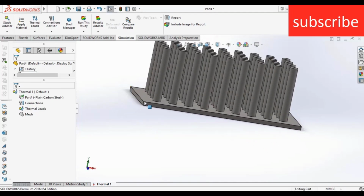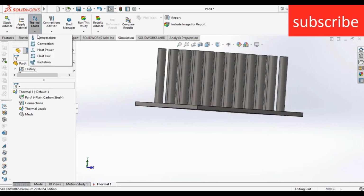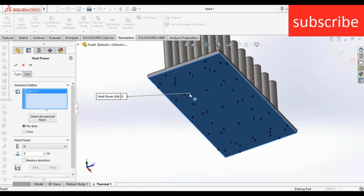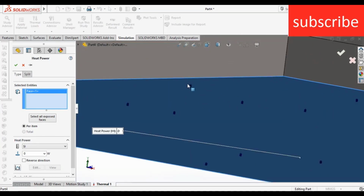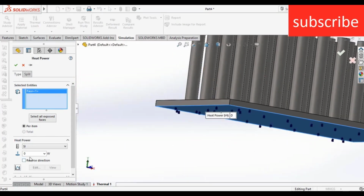Now the first thing I'm going to do is apply a load. Click on thermal loads, click on heat power. Select this face. Make sure that the arrow direction is upward. As you can see, these are small tiny arrows and their direction is upward. Now apply a load of 2000 watt.